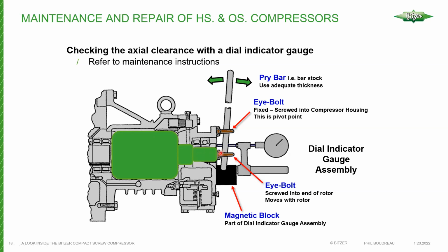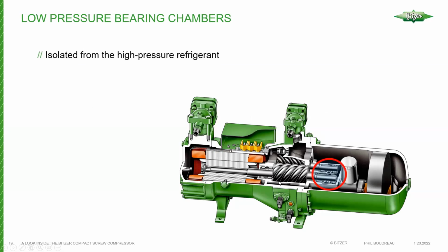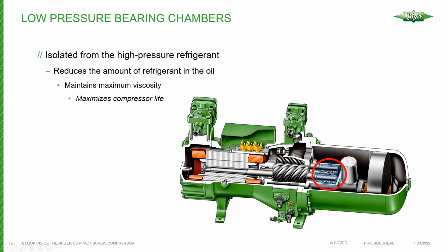And this clearance is extremely important because you don't want those rotors locking up, of course. We don't want them coming into contact with the suction spacers and that sort of thing. And note that screw compressors are designed to operate in one direction. If you turn a screw compressor the wrong direction, you can destroy it in a very short period of time. So we want to be careful at startup to make sure that the screw is turning in the right direction. Generally, what's involved there is, of course, you would always refer to the instructions for starting up the compressor.